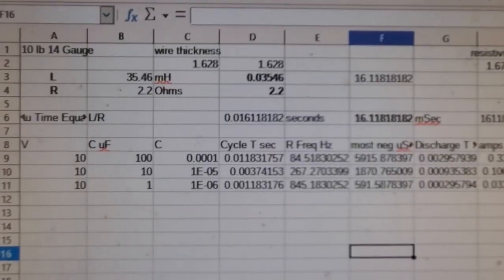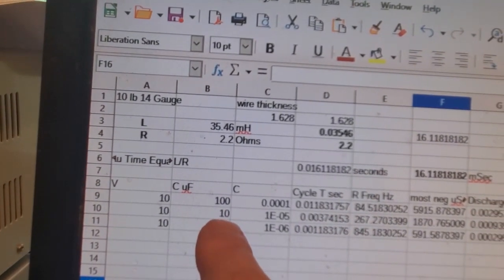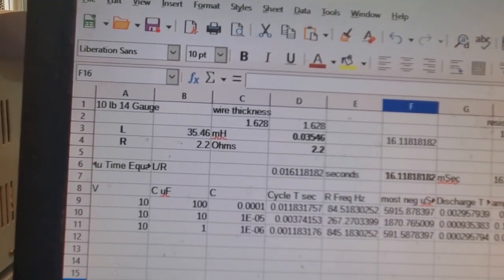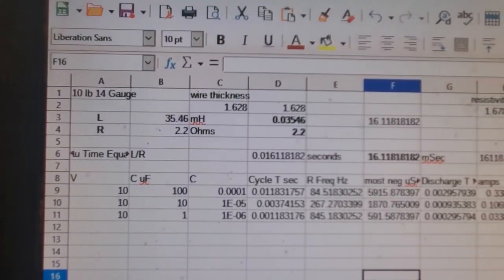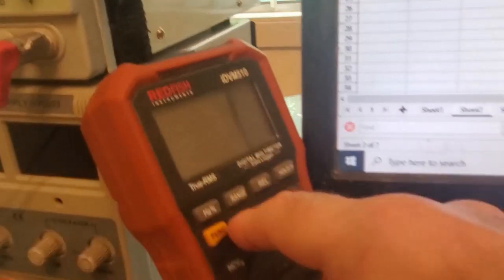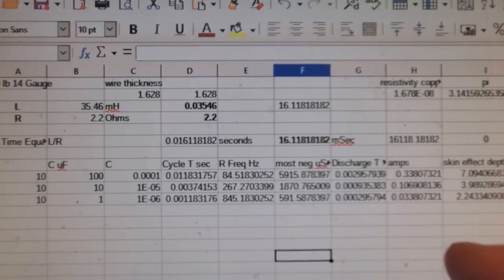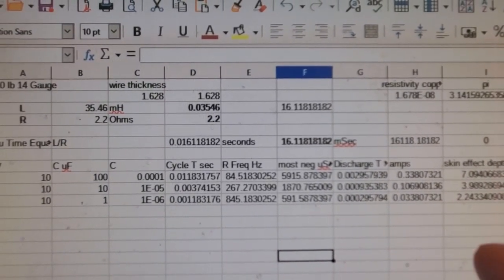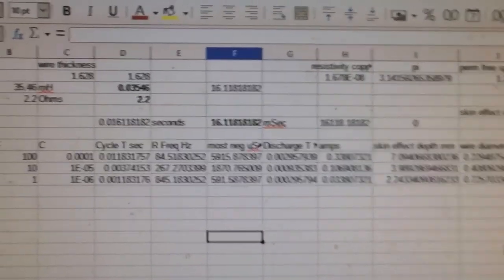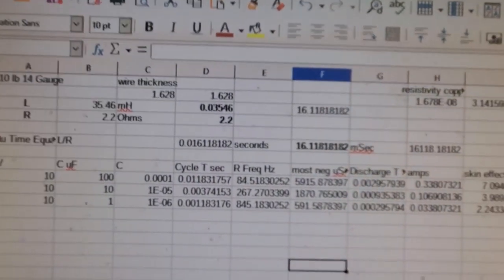But there's still another issue, and that is, let's say you put your voltmeter on the 10 UF cap. It can just about get a reading. You go down to about 4.7 UF, it'll get a reading. You go down to 1 UF, it's discharged out through the 10 mega ohm resistor here before it can stabilize on any value. So it looks like it's doing worse, but I'm pretty sure it's actually doing better. So it's not a problem with any of your components, it's a problem with your measuring equipment, that it can't measure a 1 UF cap. So what do we do there?